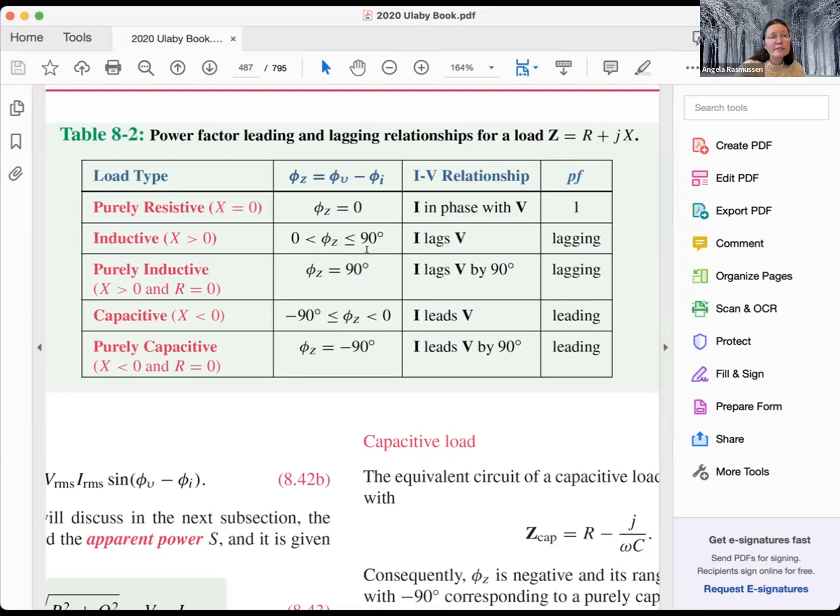In a control system, sometimes you want there to be a delay. You would want it to delay, and once it sees that delay time and wants to act on that, then you can predict exactly how long. Once I've turned on a voltage, I want the system to really turn on after everything's been charged, after 10 seconds. You could use circuitry to do that.